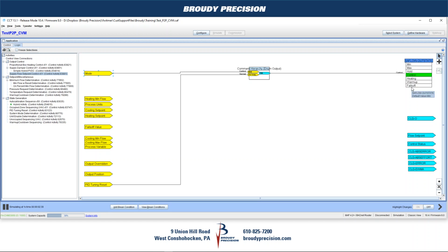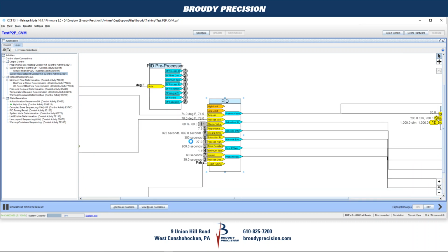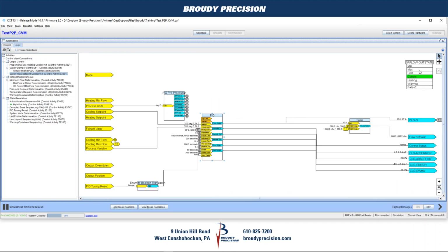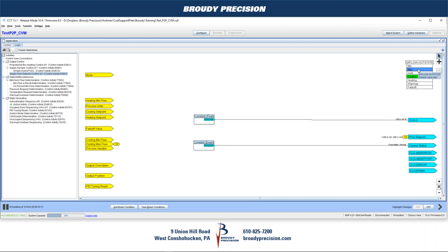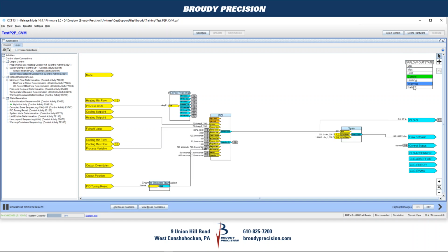And what you'll find on these blocks, each one of these lines, or some people refer to them as swim lanes, are separate wire sheets for each mode. So if we click on control, there's our wire sheet for control. And we'll see there's our PID. And if we go through, we can see everything that's going on there. We can zoom in and see where we are. And then if we wanted to go back and see what these other modes are, if we were to go to a max mode, there's our logic for the max mode: hold, min, heating, warm up.